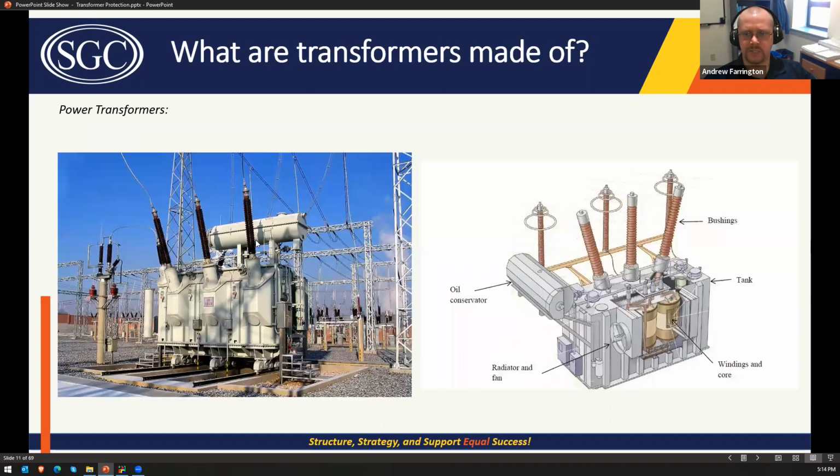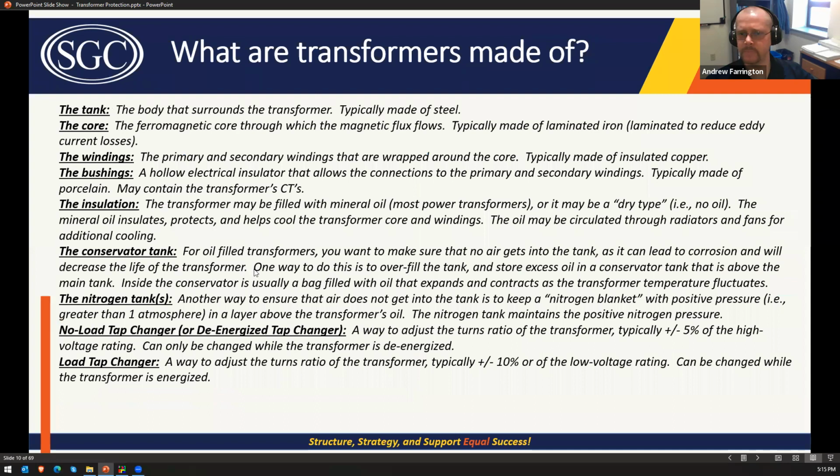If your transformer has transformer CTs, they are usually in the bushings of the transformer. So you'll have a donut CT made of iron that's got some coils around it. You have your primary current that goes down through the middle of the CT, and that is where your CT is stored, housed, whatever you want to call it.